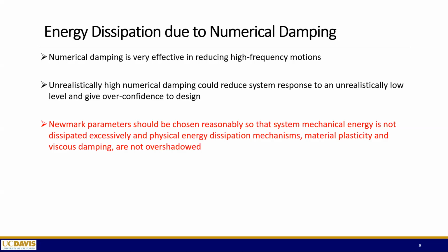But we should also be very careful because if we want the simulation to capture actual high frequency motions, we shouldn't use too much numerical damping. Just to make sure that your real response is not being overpowered by numerical damping. Unrealistically high numerical damping could reduce the system response to an unrealistically low level and give overconfidence to your engineering design.